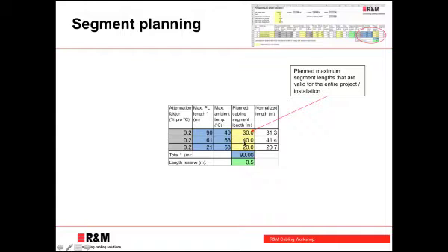Then your segment 2 would be 40 meters and your segment 3 would be 20 meters. The last line here will calculate the equivalent lengths with the higher temperature. So this 30 meters of cable is actually an electrical length of 31.3 meters with all the reduction factors applied.